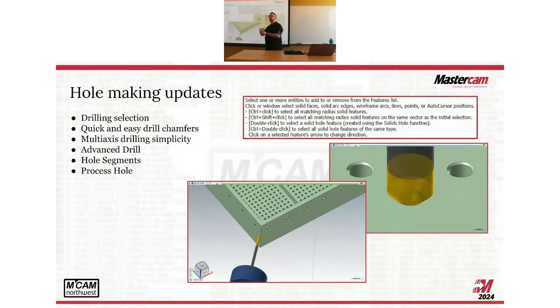But you get drill whip if you turn your drill up too fast without any support when it's a really long drill. So the advanced drill, what it can do is it creates a special output where your tool can actually slow down, go into a hole, and then speed up, and then cut, and then come back out, and kind of do whatever you want too. It's not just for that.